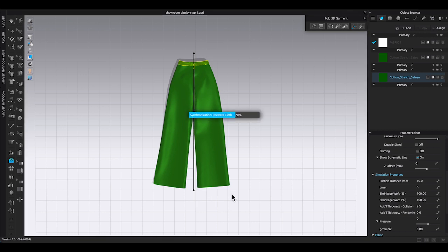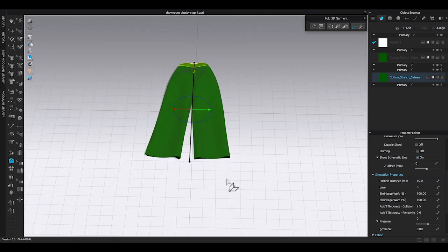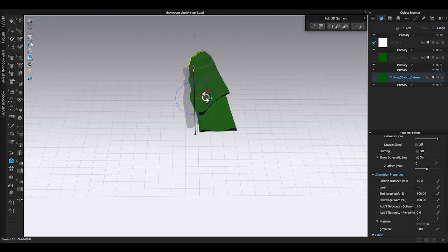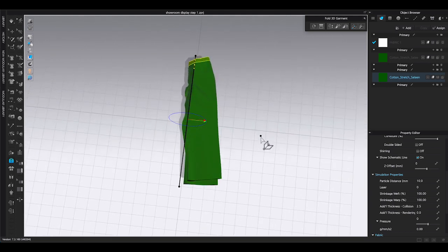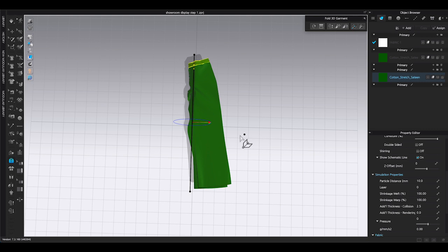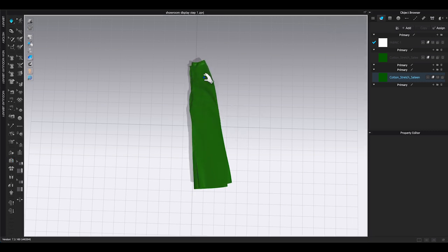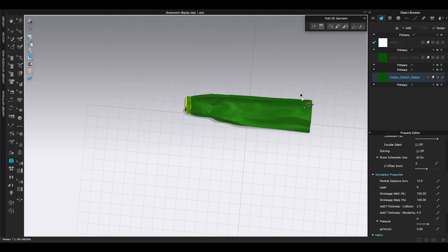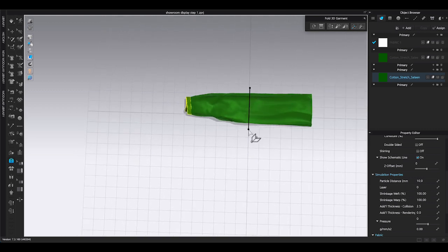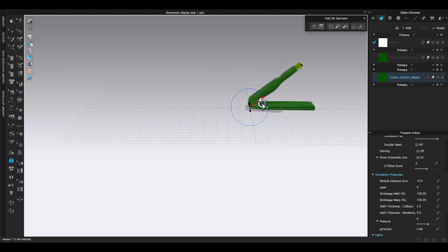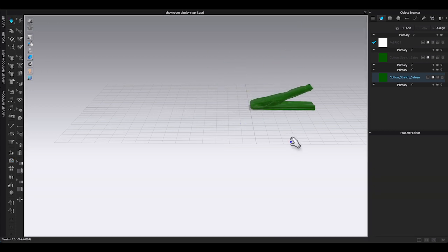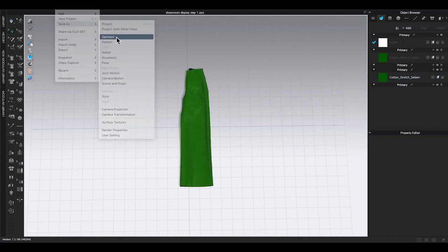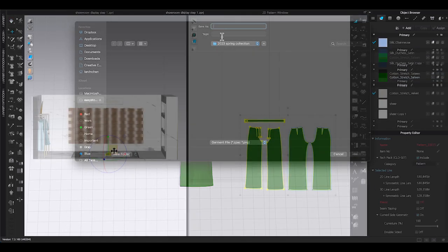When you create the fold line, you can use the ground grid straight line as your guide. Right after you double-click and generate a fold line, a gizmo will appear. It looks exactly the same as the Fold Arrangement tool. Move the arrow to fold half of the pants toward the other side. Click Simulate. And there, I have folded the pants in half. You can fold it one more time if you want to place the pants on the shelf. I will save this folded pants as a garment file and bring it back to my showroom space.